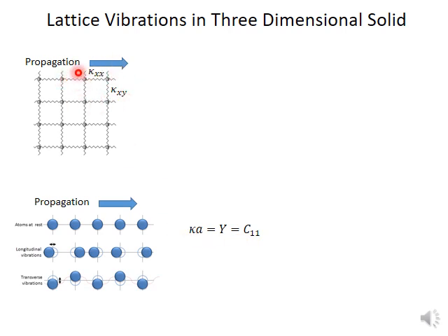Now you have a spring constant which has tensor-like properties. You can define your tensor spring constant in terms of such a relationship, not just in terms of the Young modulus, but for any component of the compliance tensor. This tensor you get from the physical crystal as part of its properties.